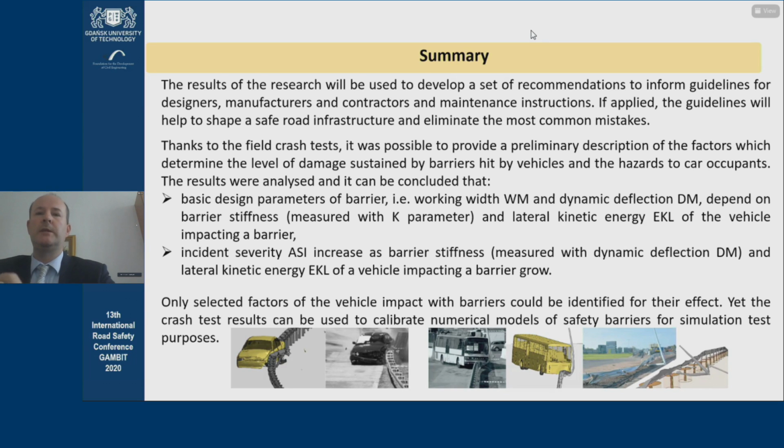So finally, the study was based on crash tests, and then we added numerical studies to complement the work. And what we know based on this is that it really makes sense to study these elements because the severity index increases as barrier stiffness increases, and working width and dynamic deflection depend on barrier stiffness and kinetic energy. So these are the findings.